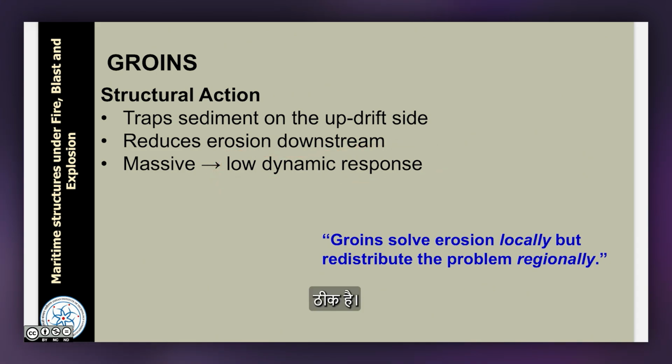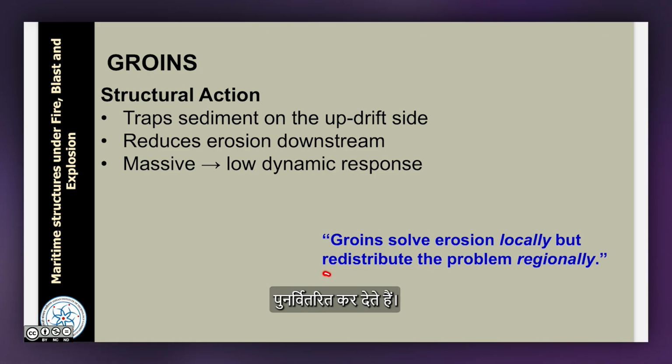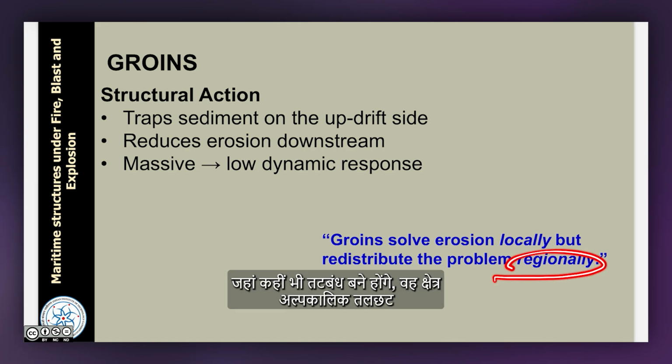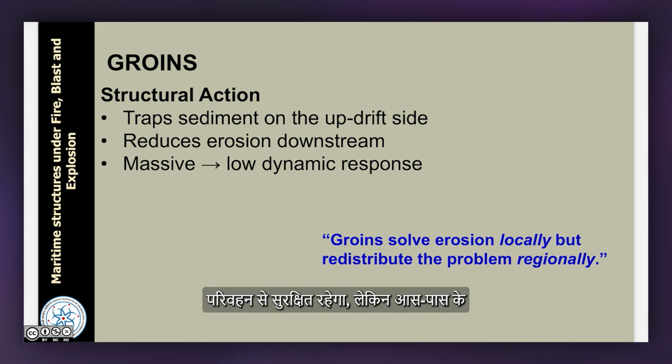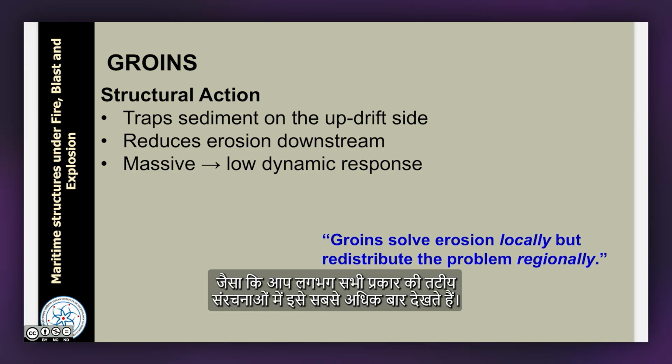Groins solve erosion locally, but redistribute the problem regionally. Wherever you have got groins, that area will be protected from shore sediment transport, but the adjacent areas will invoke more severe problems. So, that is another major issue with groins. As you see, this is common with almost all types of coastal structures.